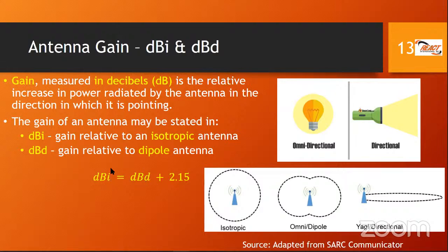So that's why some manufacturers' marketing will tell you, well, you have a 9 dB gain. 9 dB what? Is it dBd or dBi? And when they say, sorry, it's dBi. Oh, so that 9 dBi is actually more like 7 dBd then. So it's really a 7 dB antenna, not a 9. But you tell them a 9, but you just didn't tell me whether it's I or D. So we always need to know relative to what.